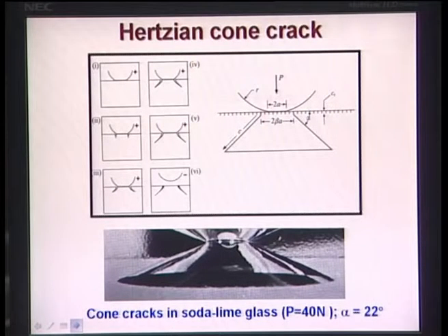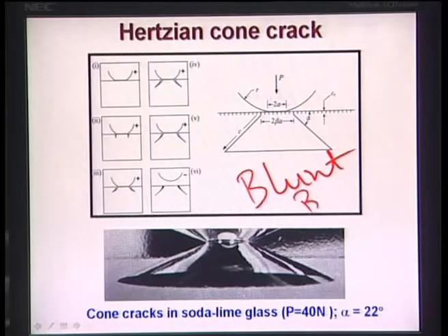Blunt indenter means like you use this Brinell indenter. So this is the case that you get for the blunt indenter, and the example of the blunt indenter is, let's say, the Brinell indenter. Now with this Brinell indenter, this plus sign means it is loading, and when you keep on loading, slowly some pre-existing cracks will be activated, and these pre-existing cracks will further propagate. This plus means loading is now completed. And then you load the flat surface more and more with this Brinell or blunt indenter.